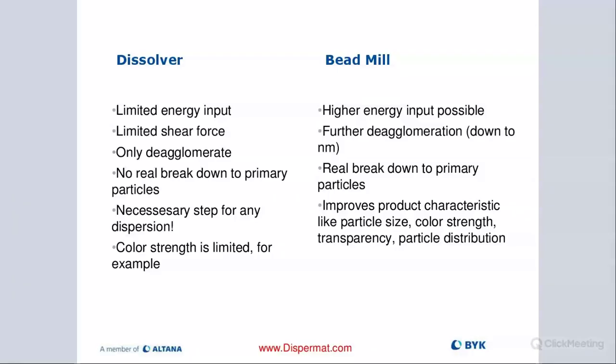Necessary step for any dispersion. We have some customers that think, hey, I have a bead mill, I'm just going to throw everything in a pot and then just run it through the mill. Most likely, you're going to have clogging of your screen or dynamic gap, and then you have to clean it out because the particles are stuck. So really important, always pre-disperse, wet out everything, and then move over to the bead mill.